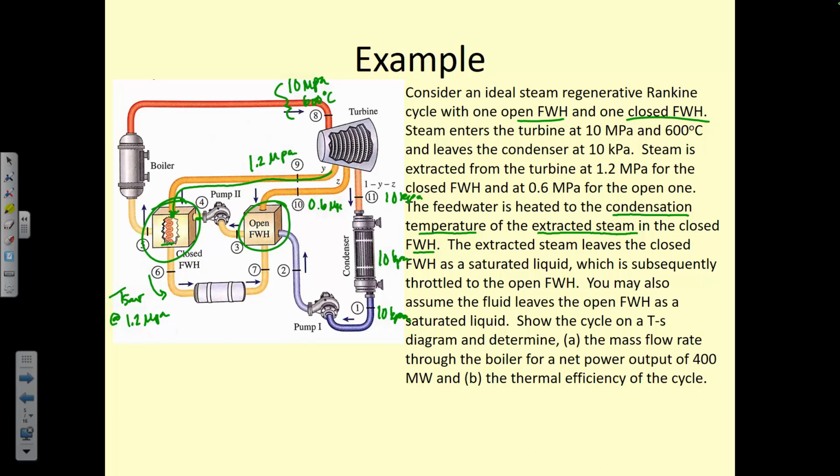Okay. So the superheated vapor does not have a saturation temperature. Right, because once it reaches that temperature, it's now a saturated vapor. So the table gives you the temperature just to tell you that that's the bottom limit for where that table can go. It's not saying that superheated vapor has a saturation temperature. Any value below this number doesn't make sense because it's a saturated vapor, not a superheated vapor. Okay, back to this.